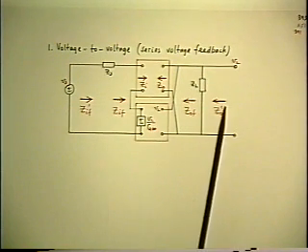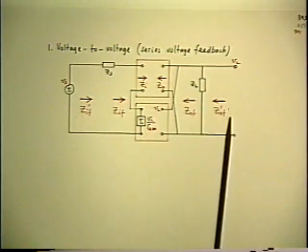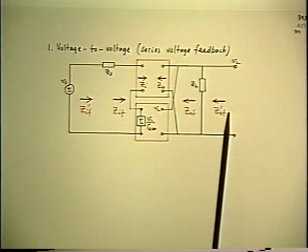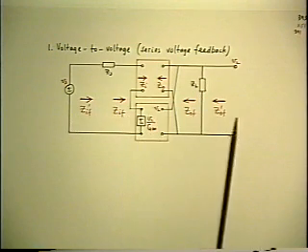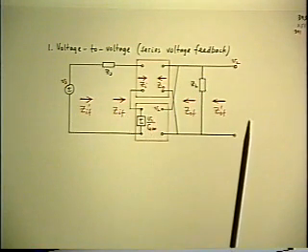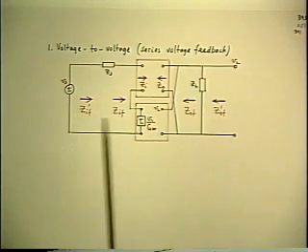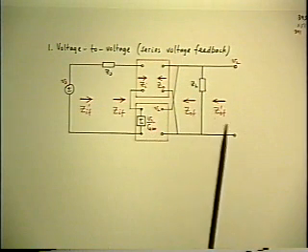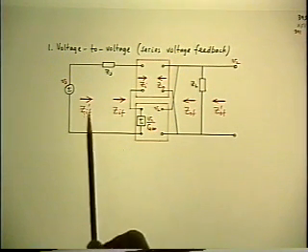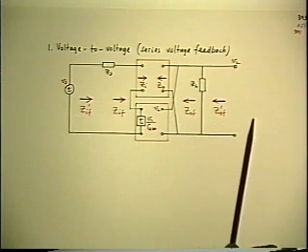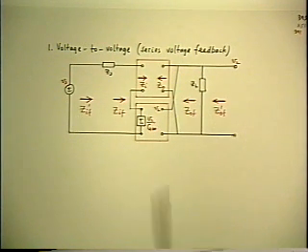So what I've shown on here now is the closed loop impedances. I put an extra subscript F on all four of those input and output impedances, indicating that feedback is going to change the effective values, and that's what we're now going to figure out. Quantitatively, what are the values of these closed loop input and output impedances?